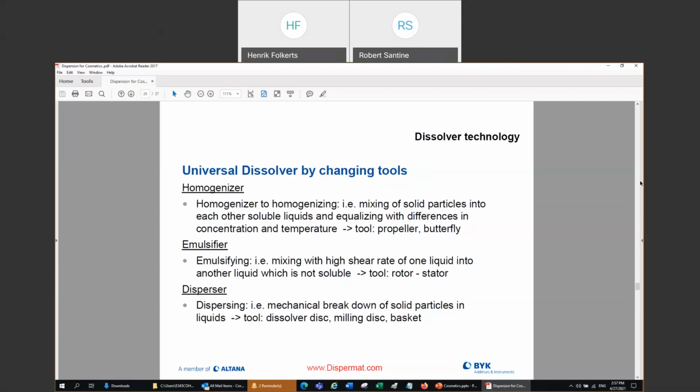So only materials where the appearance, the color, or the lightness is going to change from viewing angle to viewing angle. Most materials, if it only has absorption pigments in them, what we call solid colors, are not going to display that flop effect, so you really only need a solid color spectrophotometer, either a 45-0 or sphere instrument, to measure those.